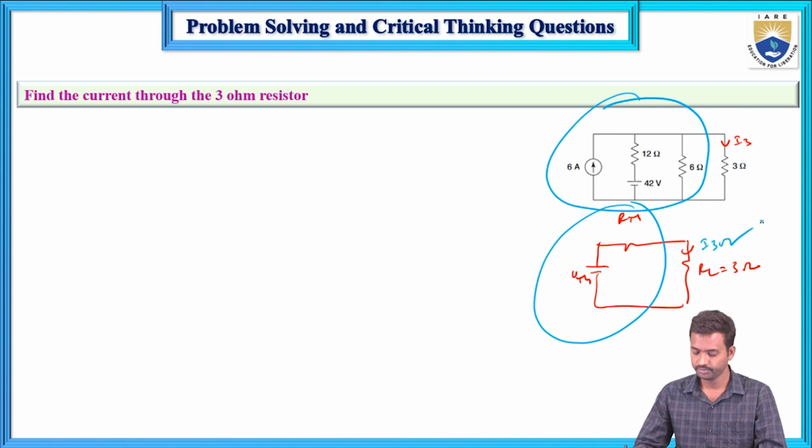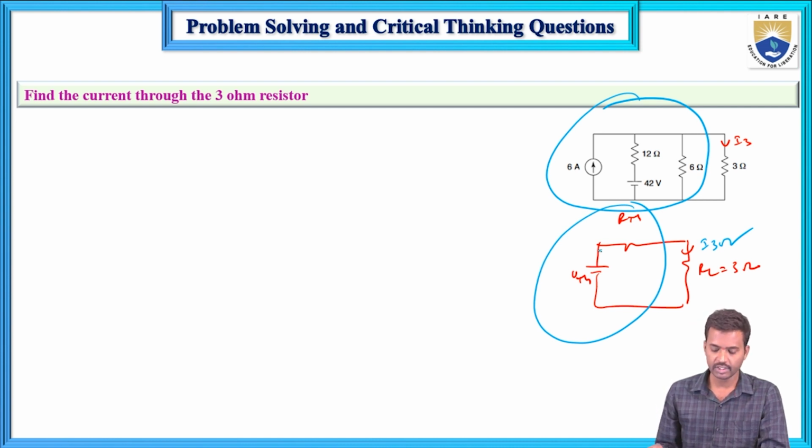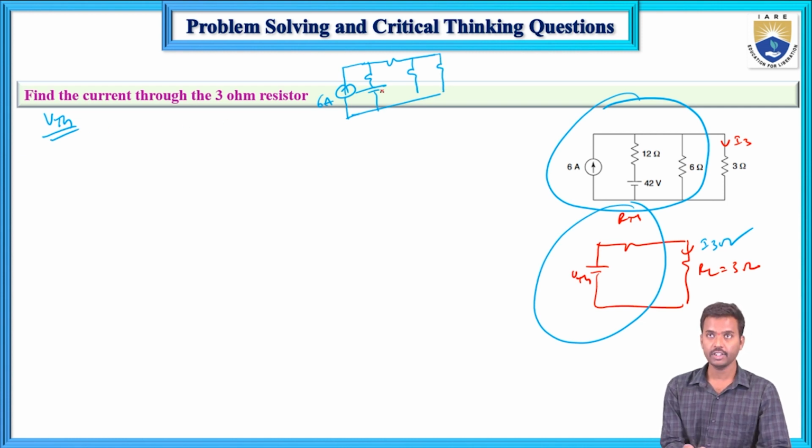First, VTH calculation: to find out the VTH, first remove the load resistance from the given circuit.